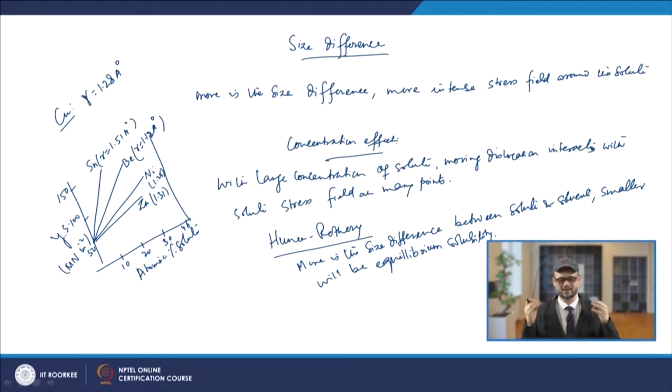From austenite you are cooling and getting martensite basically. There again you have the tetrahedral void, and you have ferrite in those cases. What you see is that the void is smaller than even the size of the carbon. So in those cases the interstitial solute atom, that is carbon, plays an important role in the strengthening of the steel.